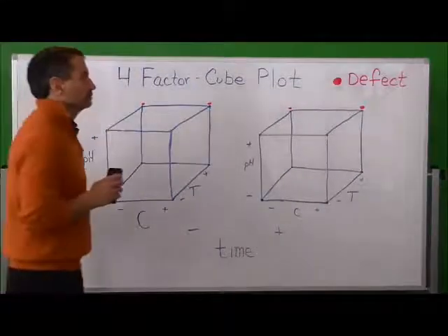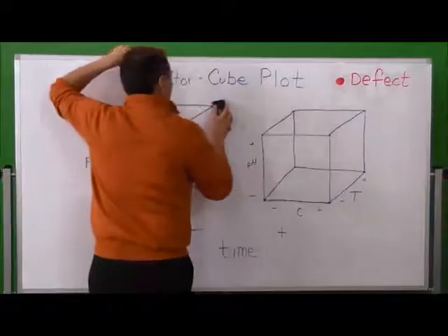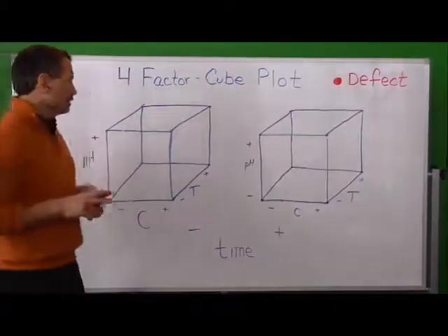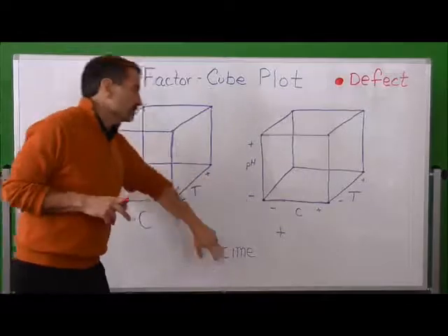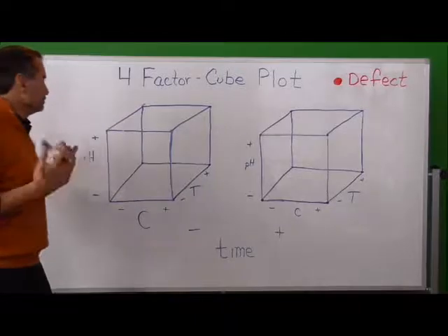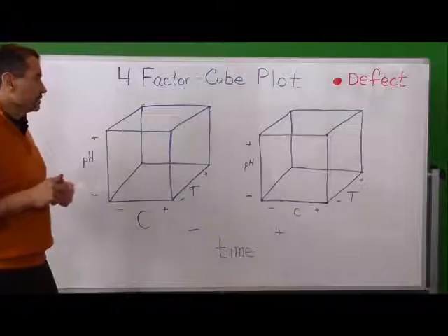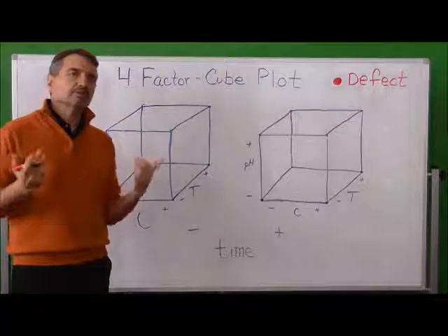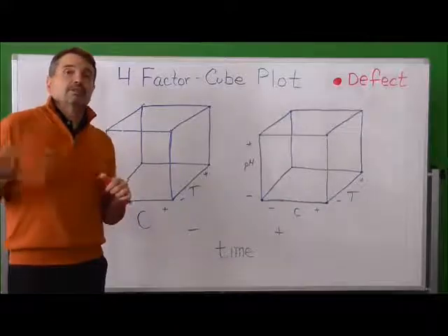That's a two-way interaction. Now there are various other two-way interactions in the entire process. You can get two-way interactions between any two combinations of them. You can get a two-way interaction between time and temperature, time and pH, time and concentration, pH and concentration. I believe there are 10 combinations that correspond to the potential interactions. The best way to find them is to plot them out and look at your Q-plot, especially on the very basic level ones that are done with attribute data, yes-no type data.